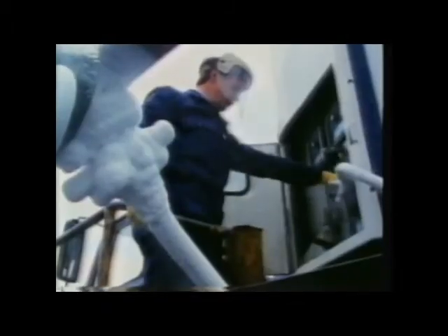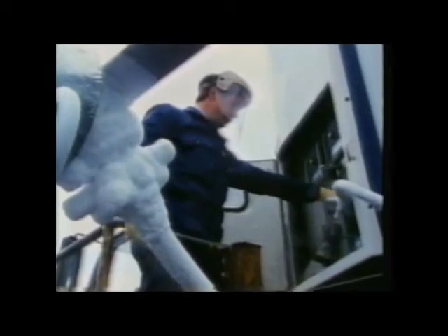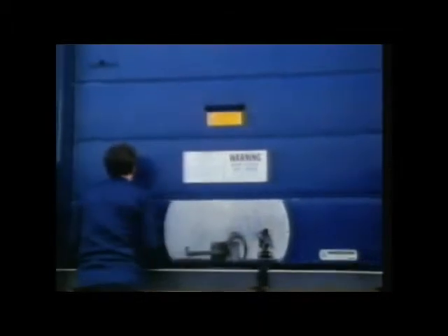Here's one use for liquid nitrogen. Big trucks are used to transport chilled foods. They have to be refrigerated. One way of doing this is for the truck to carry its own little tanks of liquid nitrogen. The tank is connected to a length of copper piping which runs all round the inside of the truck. There are small holes at intervals along this piping.